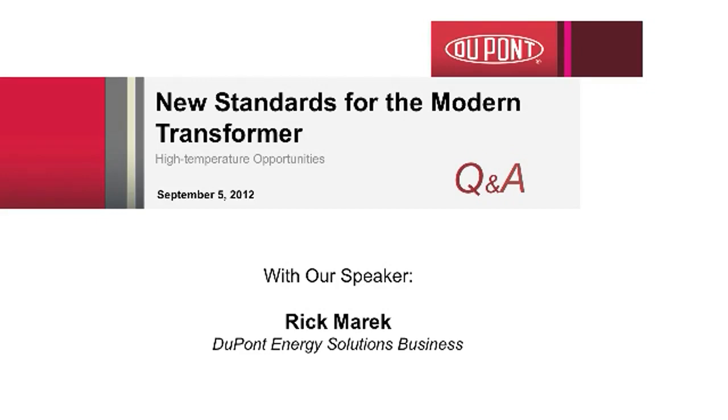And in liquid-filled applications, moisture will attack the cellulose much more than the Nomex. So moisture is always a bad actor in any case in a liquid-filled transformer, but it will have a larger effect on the cellulose than the Nomex.